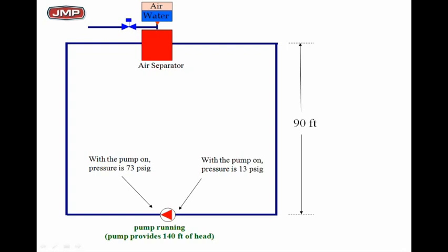13 pounds, this would probably work okay, as long as you understand system pressures are being controlled by the expansion tank. The system pressures, which are critical to controlling air and having a very happy system, are being controlled by the expansion tank and its location. That's the point I want you to understand. Nothing wrong with this, as long as everybody can accept that.